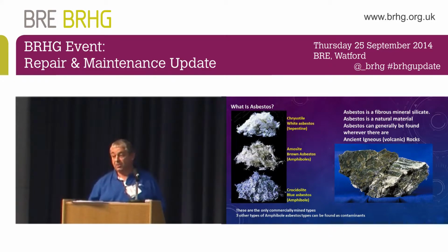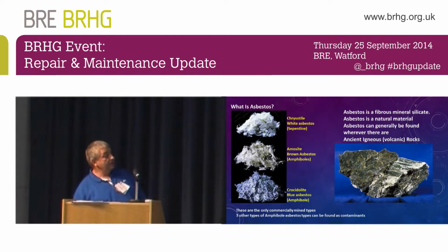So we've got chrysotile white asbestos at the top. It's a serpentine asbestos. It's the only one. An important property of chrysotile white asbestos is it's hydrophilic, so it attracts water, and when it's wet, there's no fibre release from it whatsoever. It's why the Canadians would like us to get rid of all our asbestos regulations and start accepting white asbestos again. But Europe, we will not be having asbestos back in Europe, hopefully.